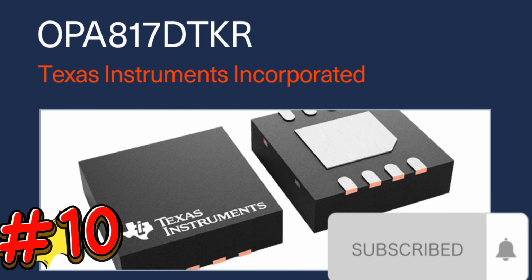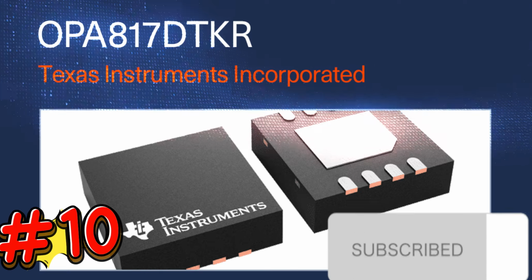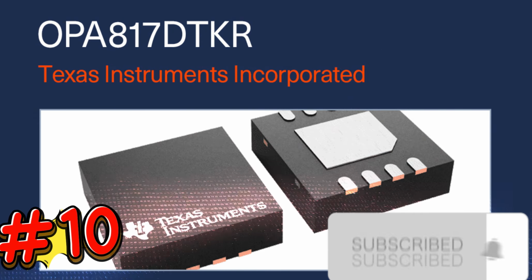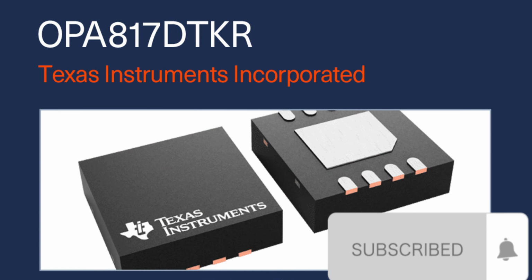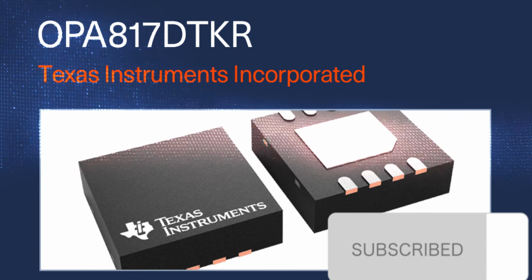This op amp offers a combination of picoamps of input bias current and low input voltage noise, which makes the OPA817 ideal for instrumentation in applications with strict requirements, such as medical and scientific testing. It is also available in an 8-lead WSON package with an exposed thermal pad for heat dissipation.